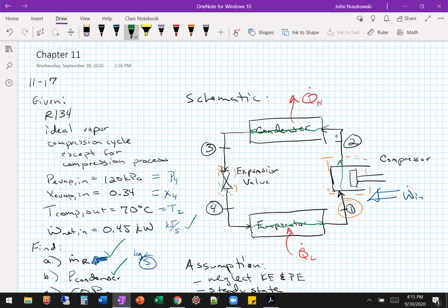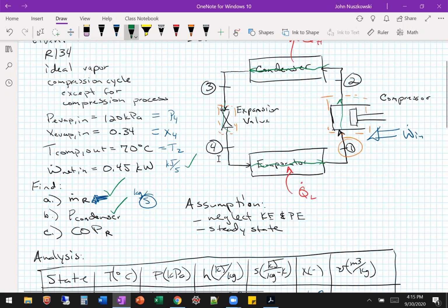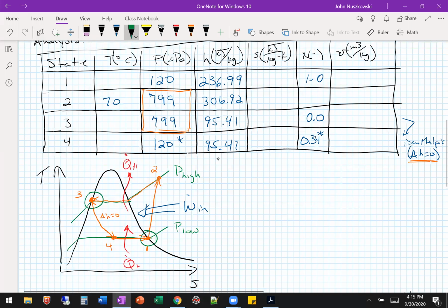Professor, I had a quick question. Can you explain how exactly the expansion valve basically makes it turn into almost like a mixture? Yeah, it's just because it drops pressure. It's just restricting flow, right? By just dropping pressure, we drop the temperature also, okay? So it's all based upon states here. Because the enthalpy is the same, we go over here.